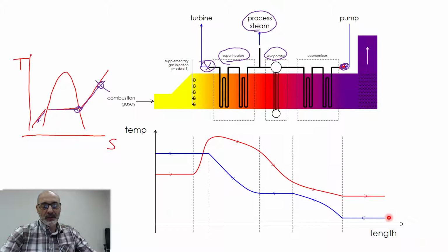So it starts heating in the economizer. It heats to saturated liquid. Then it changes phase to saturated steam. So it changed phase, and the temperature remains constant here. The temperature is not changing here. Then it is superheated to the exit temperature, right here.